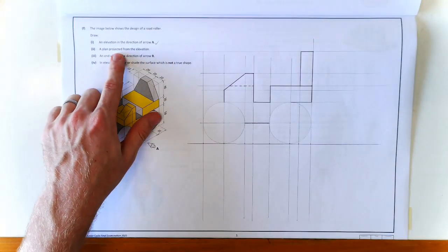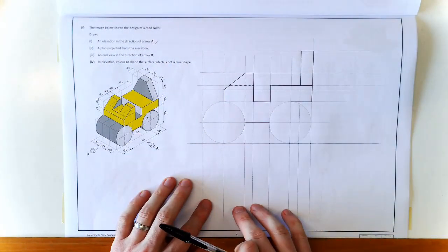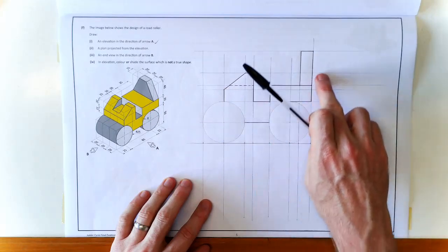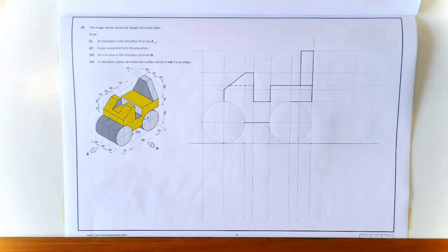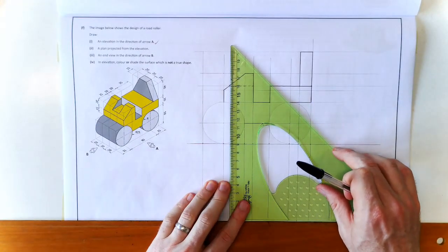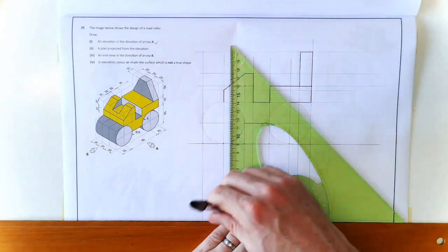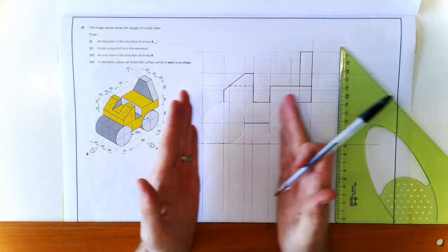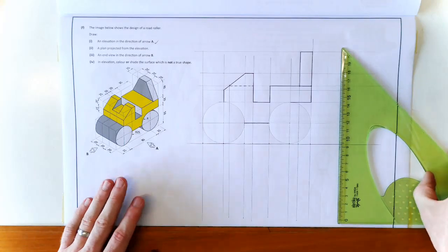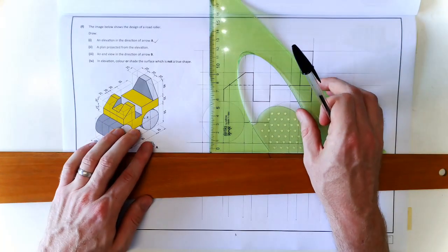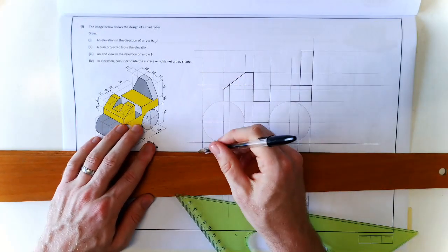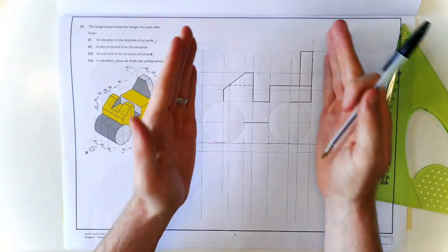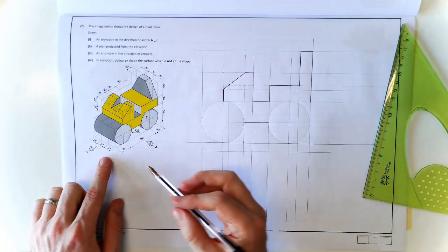We're going to project a plan. So we've projected down all of my widths. The only thing I'll need to project down now is that little piece as well, now that I've found it. Okay, so project that down. And all my other width or length has been projected down. Okay, we'll typically put about 10 millimeters between the elevation and plan. So here's where I'm going to start taking the measurements from. So I have my heights, I have my lengths. Now what I need is depth.